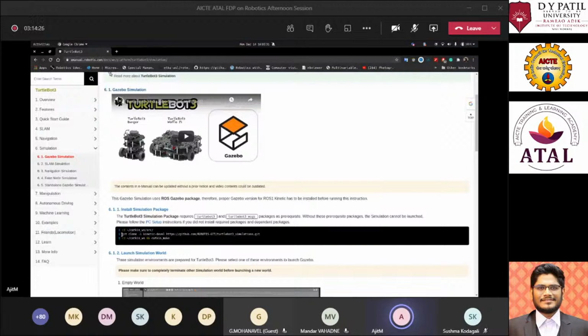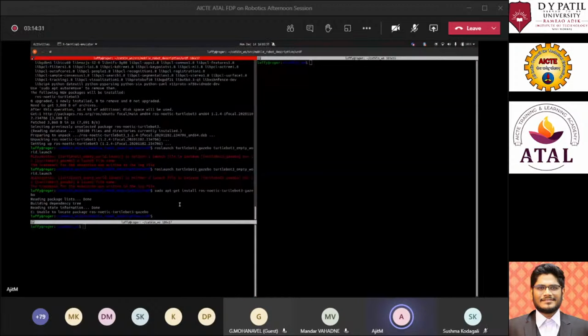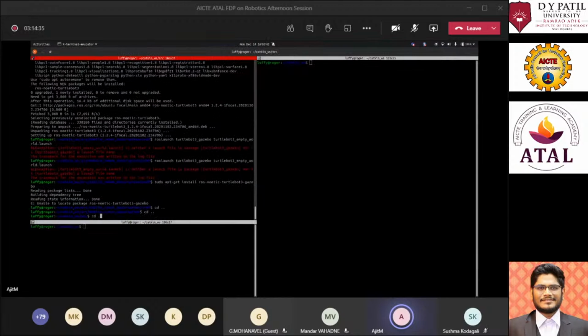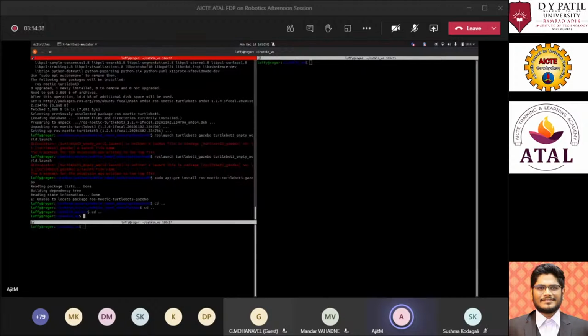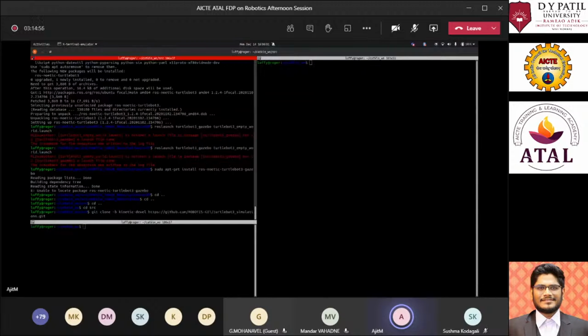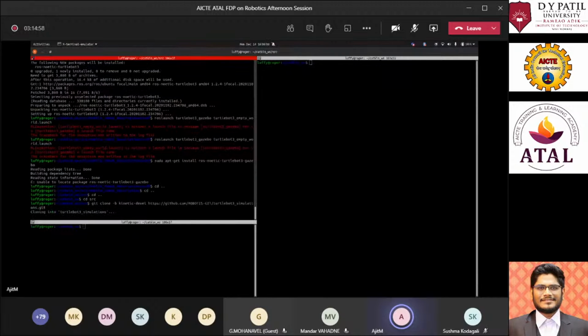Okay, so they have provided it differently, not with the ROS distribution. If you have a package which they have provided separately, you can just git clone it. Now think about adding packages which are not provided in the ROS package system. If you want to add that specific package, you have to go into the source of the catkin workspace, and over there you have to clone that specific package.